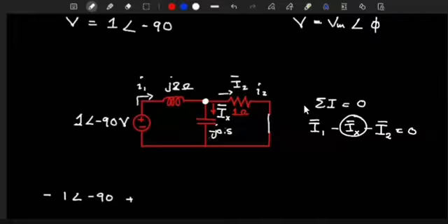I was just trying to make it different from the actual one. Because the Ix we are looking for is a function of time, in the time domain, but the one we'll find using this approach is the phasor current, its phasor version. What about the currents I1 and I2? These are defined. We've just defined them. We're not interested in them. We defined them since you chose that I use Kirchhoff's voltage law.